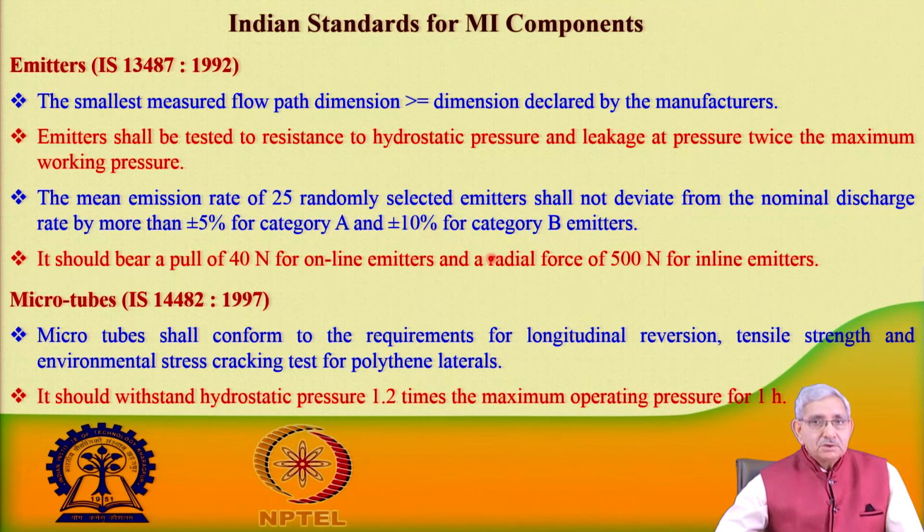If it exceeds 10%, then the dripper should be rejected, and then a new dripper should be developed or used.